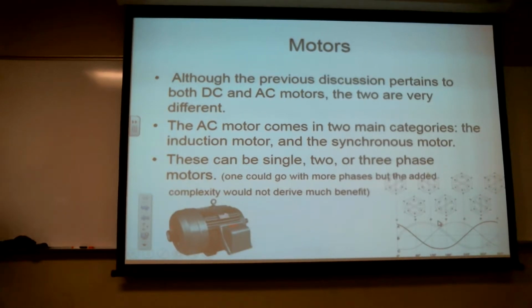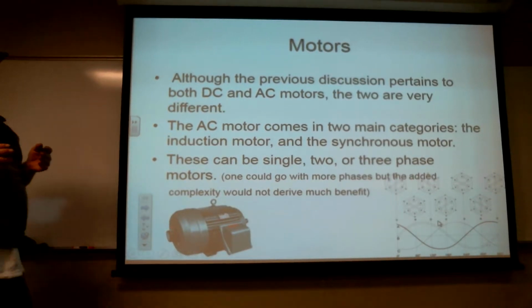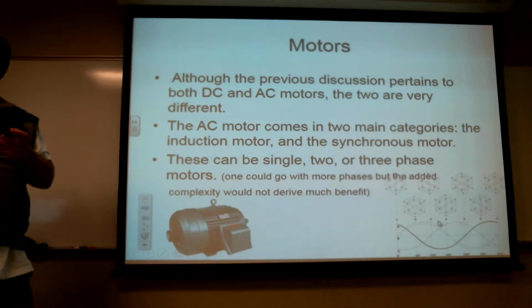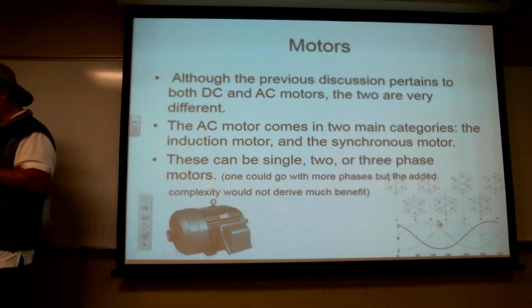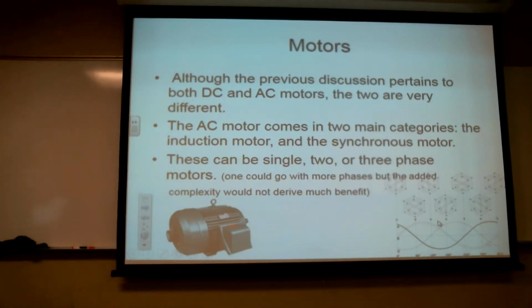So, three-phase motors, we're not going to worry about too much because they'll do exactly what you do in terms of wiring them. And if it's backwards, you just reverse 2 leads, any 2 leads. Any of the 3 leads, reverse 2 of them, and it'll go the other direction. You'll begin to see this here in a little bit when we start talking about single phase. So they just had to go out to the main panel and switch the leads.